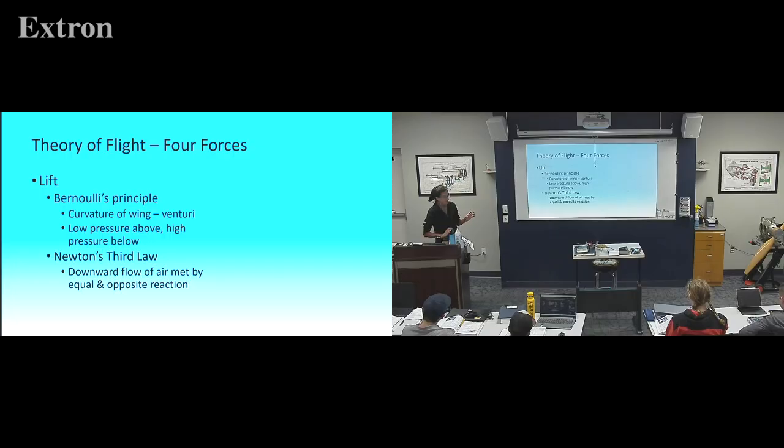So I'm going to draw a bunch of this out, but first of all, Bernoulli's principle and Newton's third law are the two ways your textbook, the FAA, chooses to describe lift. We're going to talk about airfoils a whole lot more, but air is coming this way, up and over our airfoil, not all shapes of airfoils. Bernoulli's principle says that because of the curvature of the wing, we have low pressure above and high pressure below. That causes lift to occur.